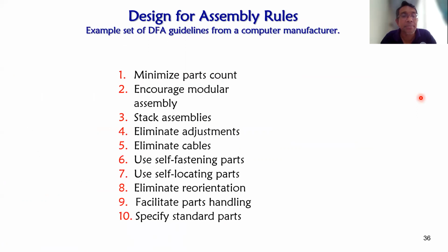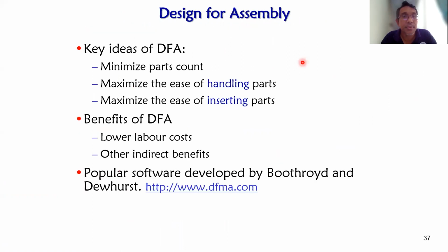And then design for assembly rules, they have these rules. The key ideas for DFA, to conclude, we have: minimize the part count, maximize easy handling, maximize easy inserting.